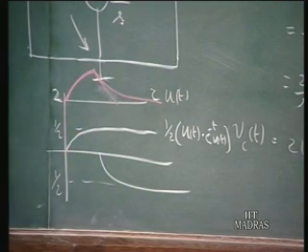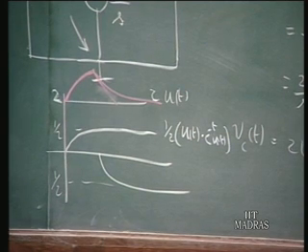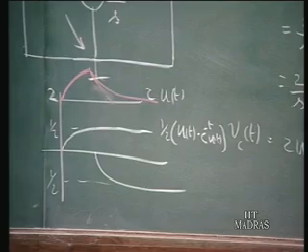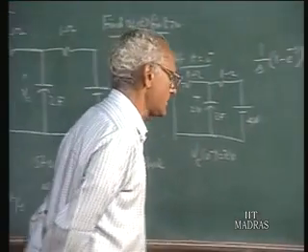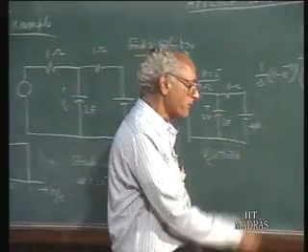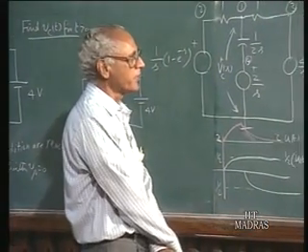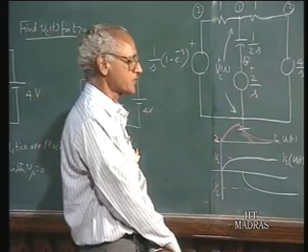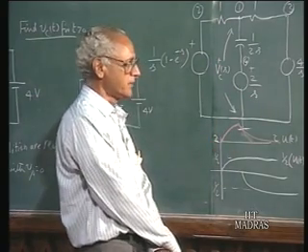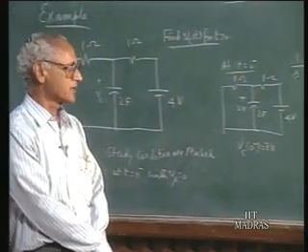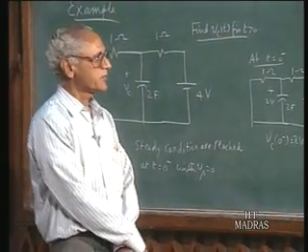This problem illustrates how you can handle the solution when there is a discontinuous time function, and how, when finding the inverse Laplace transform where e^(−s) or such terms are present, you can use the property that e^(−s) means that particular function of time is delayed by 1 second. If it is e^(−ts), it is delayed by t seconds.